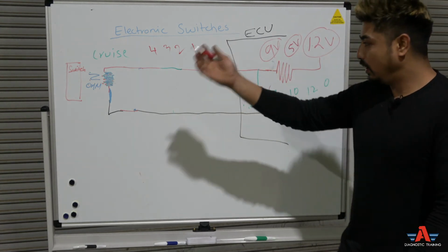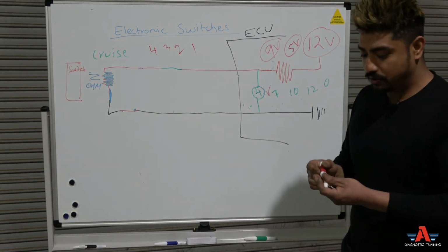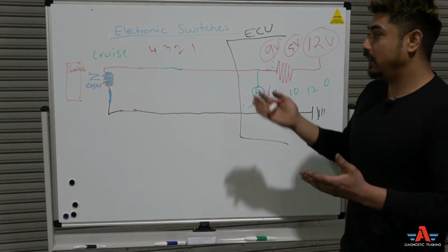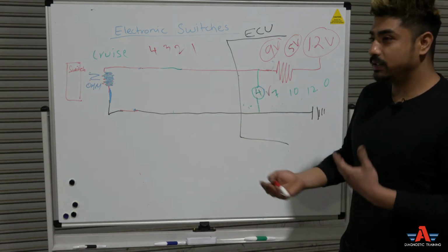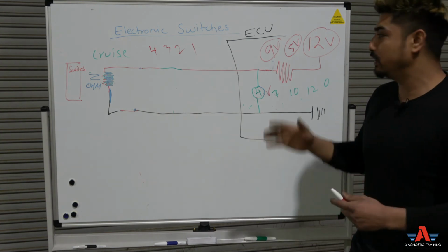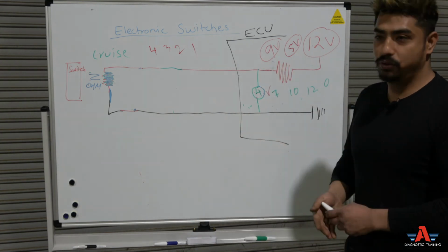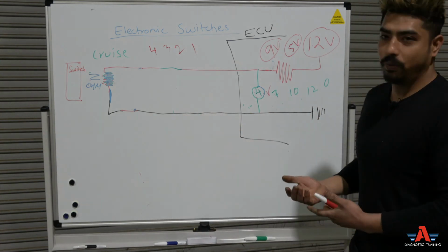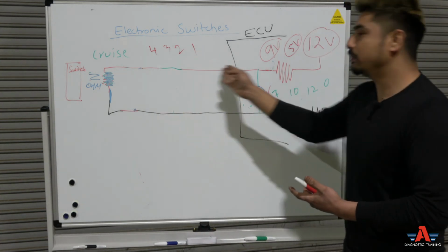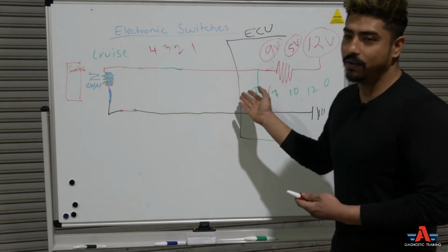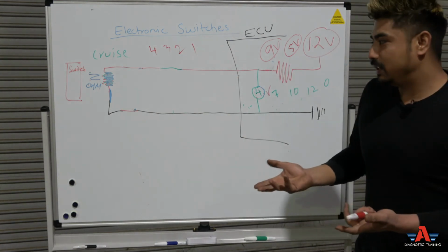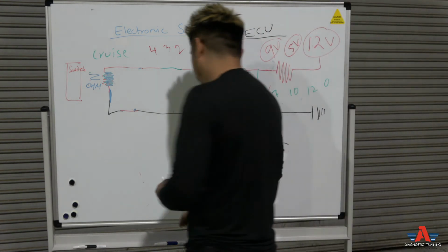You can use all this testing, everything I showed you today, on any electrical switch, and you can do your testing, bypass testing, actuation, everything at the switch itself. Okay, and from there, obviously, if you have a problem with the wire, you're going to chase it towards the computer and the wiring. But most of the time, more than likely, the component is faulty. Okay, in this case, it was.